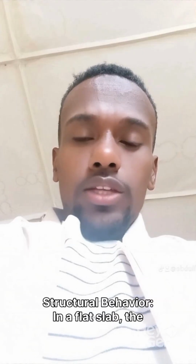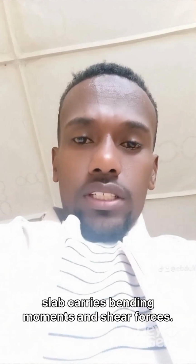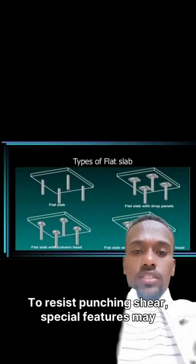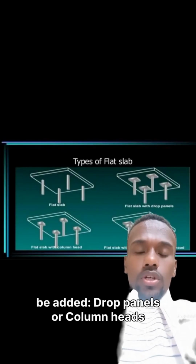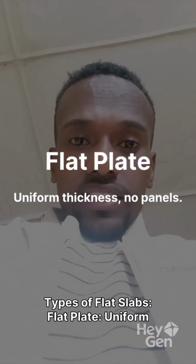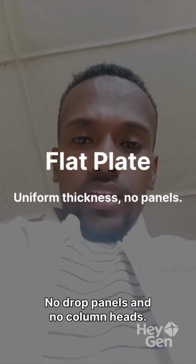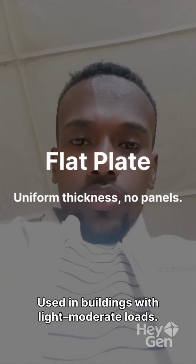Structural behavior: in a flat slab, the slab carries bending moments and shear forces. The highest stresses occur around column supports. To resist punching shear, special features may be added: drop panels or column heads. Types of flat slabs: flat plate, uniform slab thickness, no drop panels, and no column heads. Used in buildings with light, moderate loads.